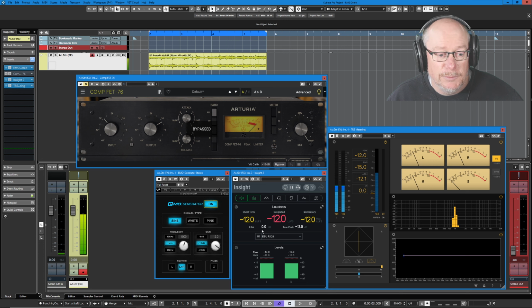Here's one immediate problem. The moment you start looking at loudness, be very careful to presume that what you're seeing is actually -12. What we're getting here is something called a K-weighted loudness curve, and it just so happens that at 1 kilohertz, the test tone that's being generated here, that generates a reading on these meters of -12 loudness units.